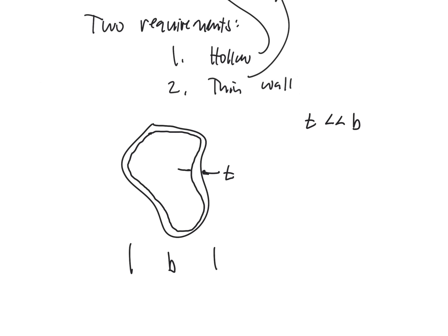So an eggshell, if it were going under torsion, a Mountain Dew can that's been cut off at the ends, a paper towel roll, things like that. They have a thickness that's relatively small relative to their radius or their diameter. But T can vary. So let's put that as item number 3. T can vary,